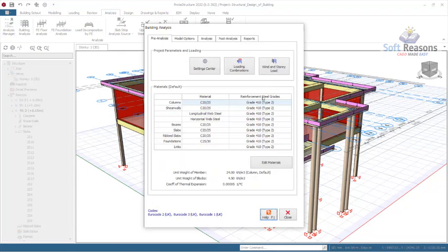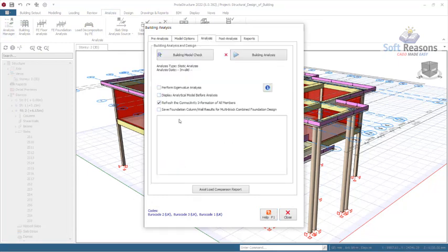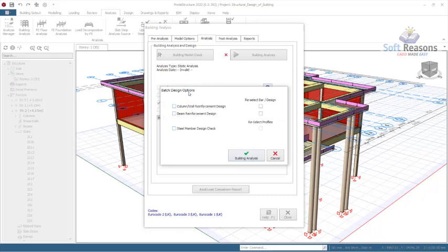So click on the building analysis again. Go to analysis tab. So now just click on building analysis to carry out the analysis of the structure successfully. So you have this batch design option. If you want the program to actually analyze and design the members, you have to get all of this selected. But you can first check your structure after analysis before you start designing.